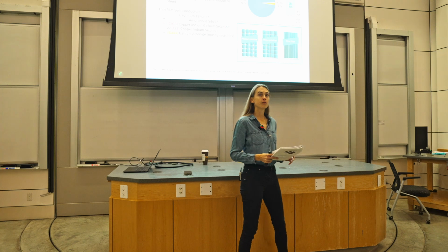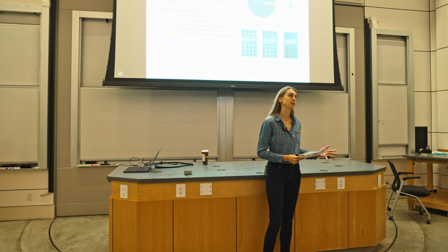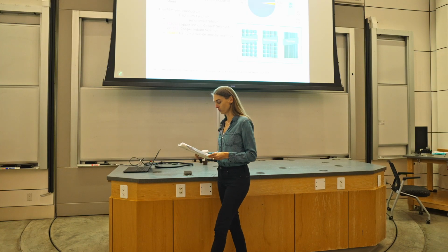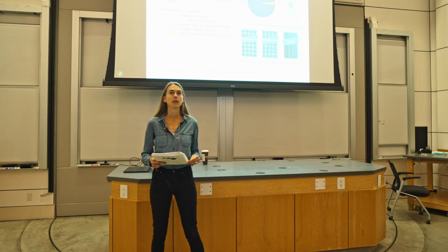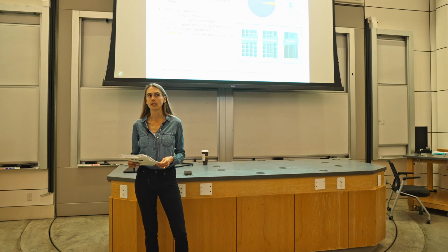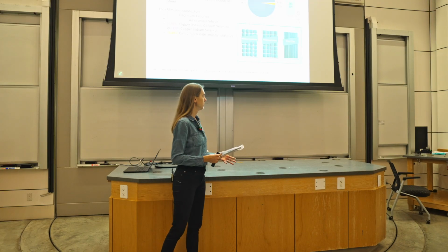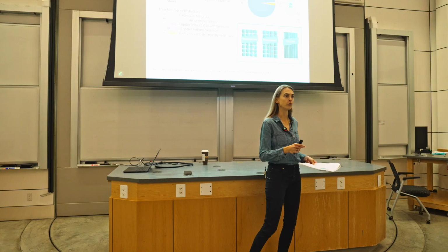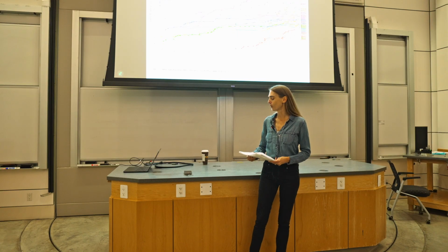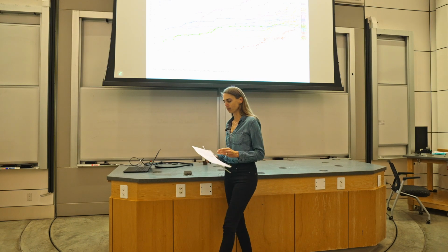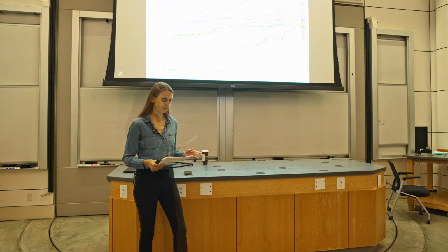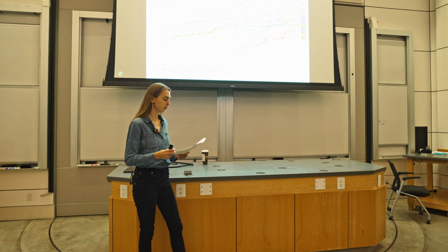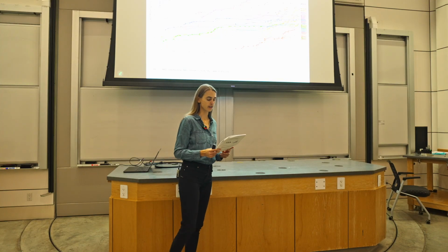There are a variety of factors that might lead you to choose one type of material over another, including cost, but also things like temperature sensitivity and how power output degrades over time. But a really big factor is efficiency, the efficiency of converting solar energy into electricity. So let's dig into this concept of efficiency of solar panels. As we talked about earlier, higher efficiency means greater power output per square foot of PV cell.